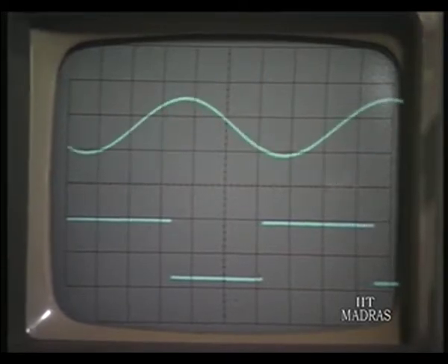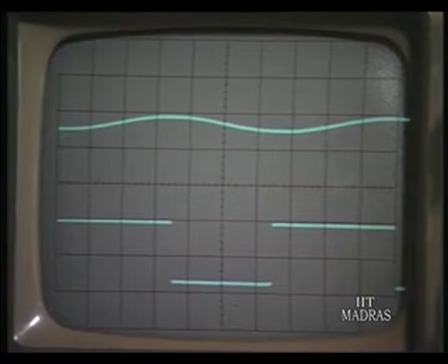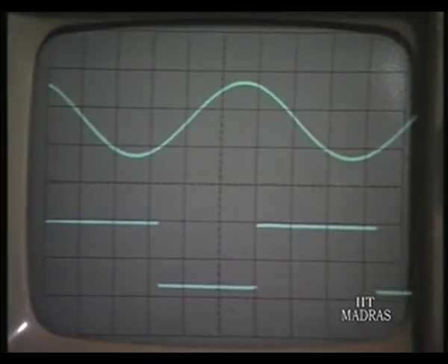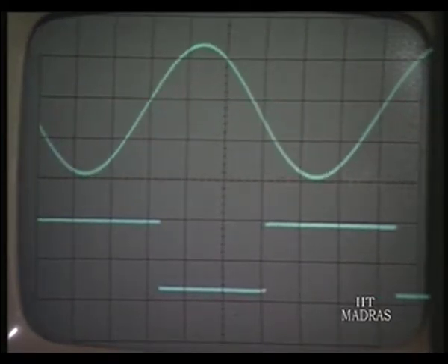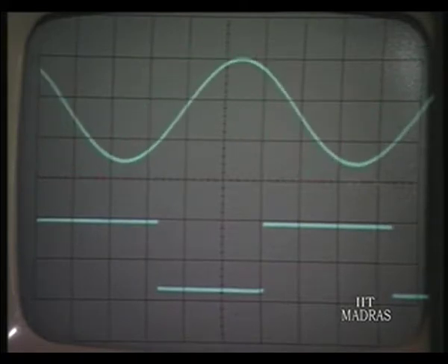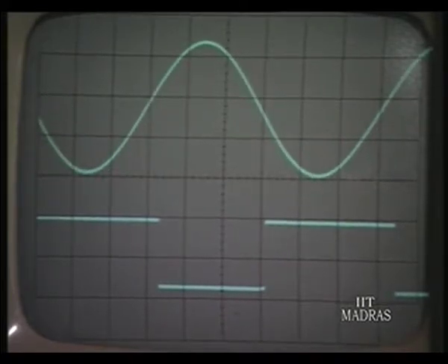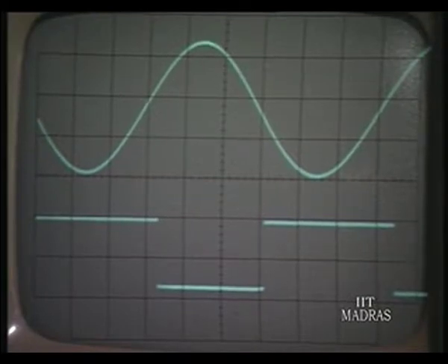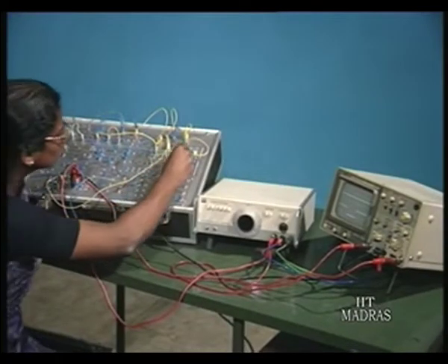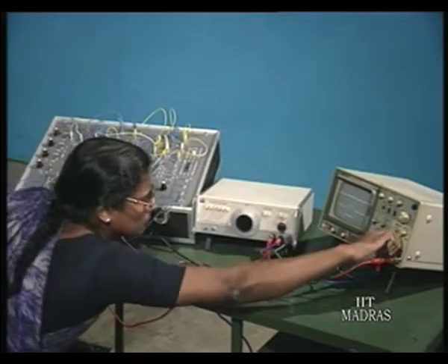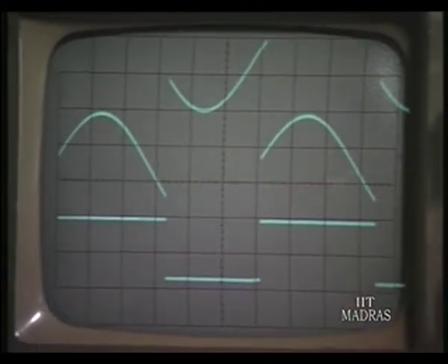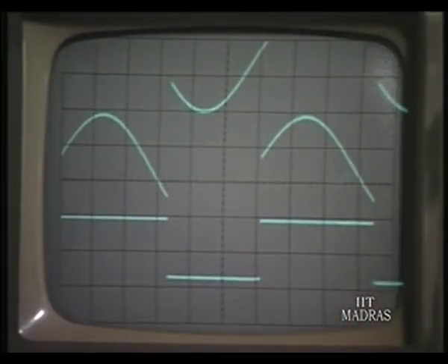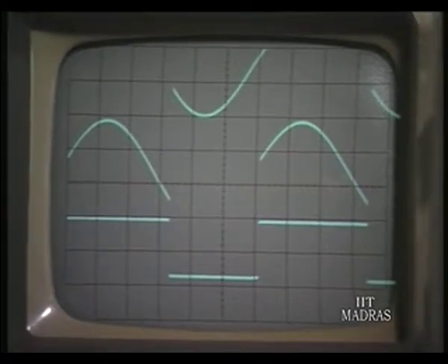This is the center frequency. On the other side also it rapidly falls. See, it rapidly falls. Again tune it, please, exactly, tune it exactly to the center frequency, so that you get the highest fundamental output. Now, let her show you the notch output. The fundamental has been eliminated, so only the harmonic should be there. Their output amplitude should be extremely small, and therefore, she is changing the scale so that the small amplitude of the harmonic content can be shown to you at the output of the notch, and you can see that waveform exactly as I had shown you on the board.